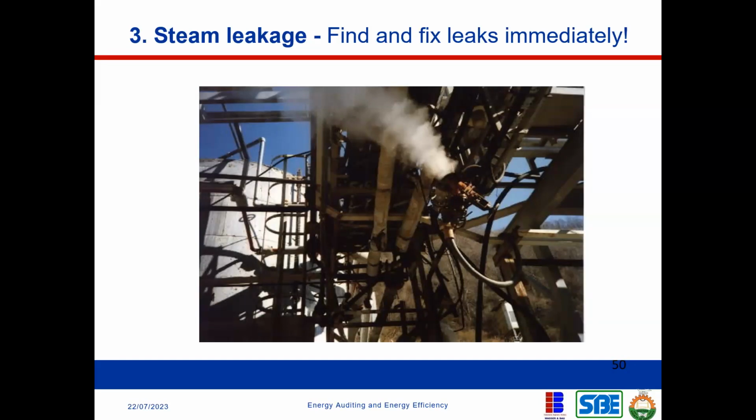You could have steam. So when you see this kind of thing, in fact, this is bad. Some you might not be able to see, but you might hear a whistling sound. Okay, you know that there are steam leaks. So these are areas through which energy has been lost in the steam systems, so you need to pay attention. Sometimes there are instruments that you could also use to detect very tiny orifices in the steam distribution system where leakages are taking place. Okay, so you need to detect if there are leakages in the steam system and they have to be fixed.